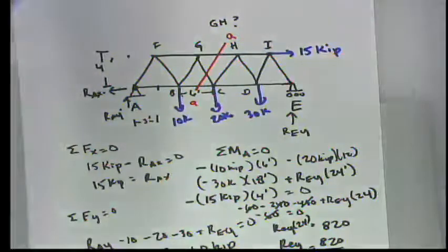becomes a force. Yes? So in order to solve for sections, do you have to find all the external forces on the joints first? You have to at least find all the external forces on one side of where you're cutting. Okay. Yes, that's a really good point. If you have a way, like, let's just say, here I couldn't do it, but if I was able to find RAY and I didn't know what RAY is, it wouldn't matter.